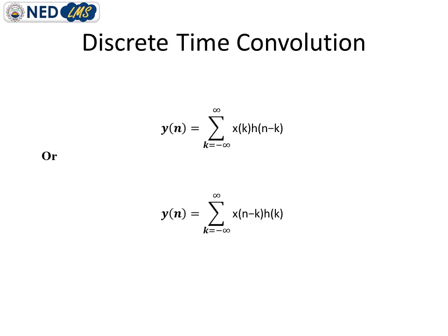For calculating discrete time convolution, we can either use the mathematical expression y of n equals summation of x of k into h of n minus k, where k varies from minus infinity to infinity, or use the second formula in which x is shifted and the impulse response remains the same. So we have the choice to shift either the input function or the impulse response.